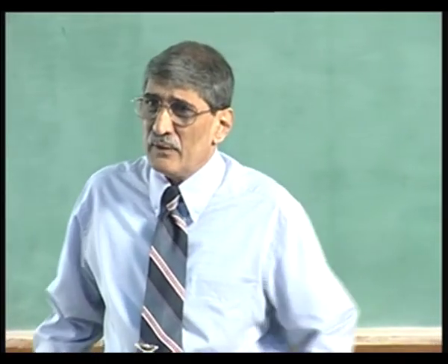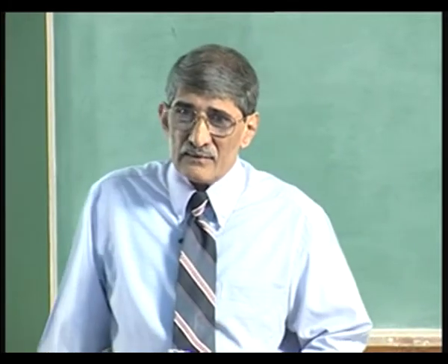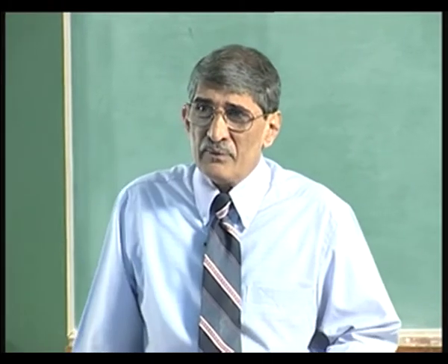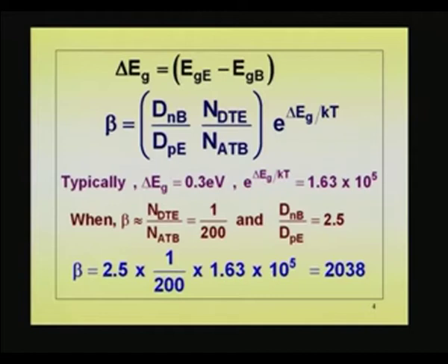In fact, in the bipolar conventional transistor, you have a problem the other way. You have a problem where the band gap in the emitter is smaller than the band gap in the base, due to the heavy doping effects. So, in fact, when you do a device like this, you overcome even that. Just to point out what actually is happening, just one or two sentences I would like to bring out.